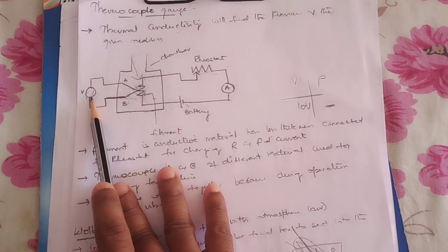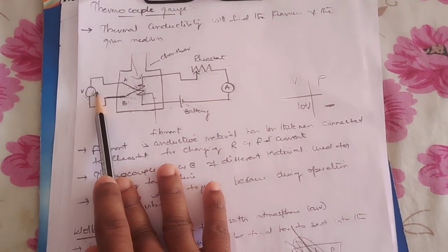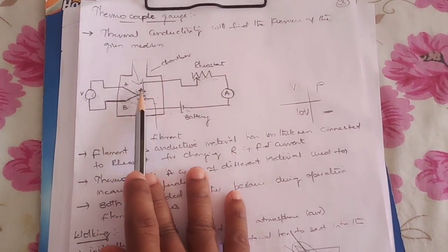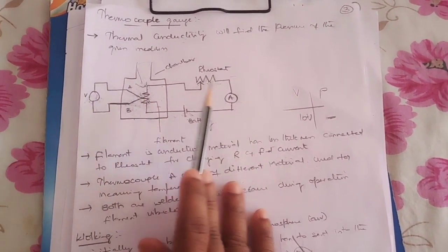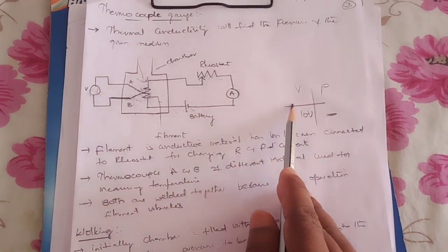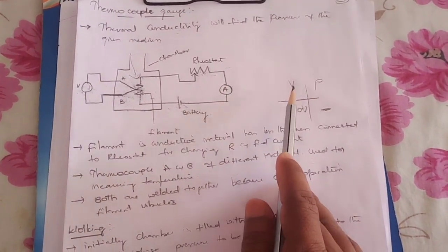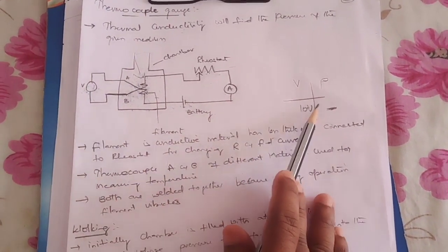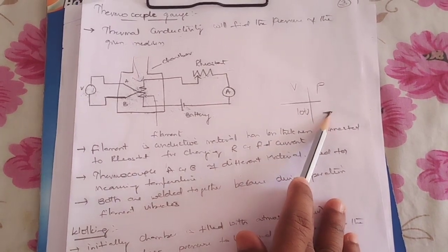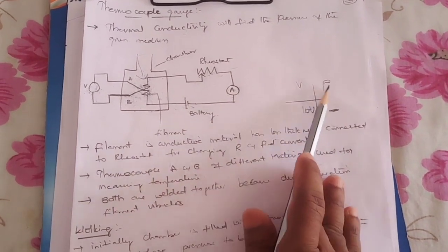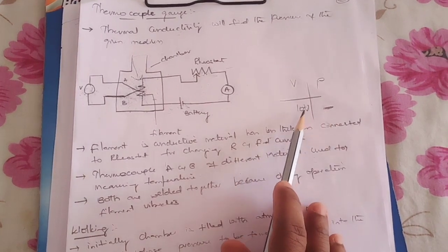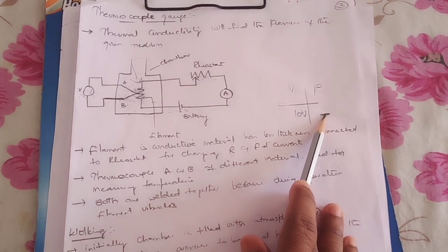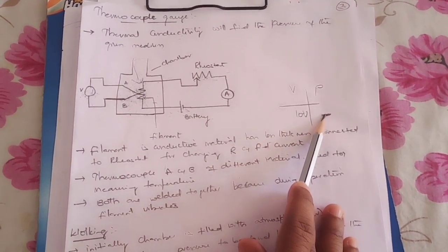It displays the value in terms of voltage. Whatever value is displayed in terms of voltage gives you the value of the pressure of the particular medium we are sending into this chamber. Let us say it has some calibrated scale representing voltage and the corresponding pressure. If it is measuring some 10 volts, these 10 volts will give the corresponding pressure value. There will be some tabulated readings in the industries indicating a particular voltage. If we get some particular voltage, then it shows the particular pressure measurement.